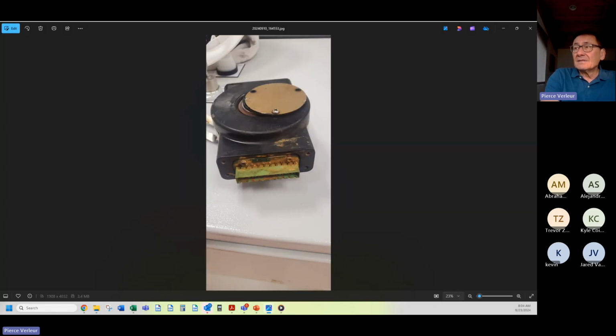However, these encoders were in the weather. So we're shipping them new encoders that are IP67. They also have to be class 1 div 2 because it's an explosive area. But yeah, that caused some problems too. So anyway, I hope we've made a case for you to consider the output characteristics of the VFD to the motor called the tank circuit, the impedance, the capacitance, and the tools like special cable that you use to make that circuit perform correctly. Thank you very much.